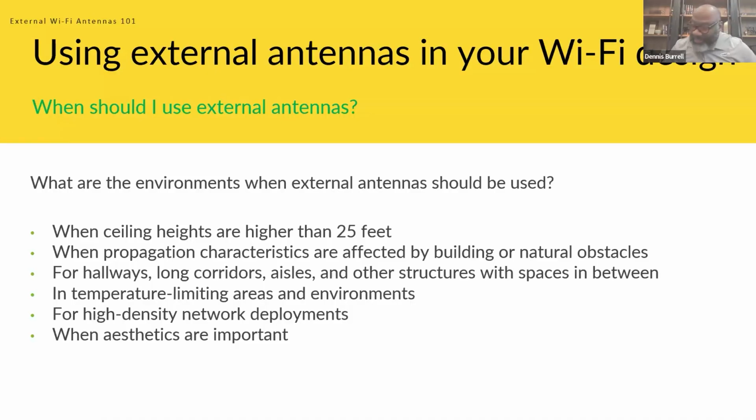For an omni antenna, let me give a little example. Typically when we do omni antennas, that radiation pattern looks like a donut. You've got your donut here. The thickness of the donut is your vertical. The hole of the donut is that null at 0 and 180 degrees. And then that circumference is your horizontal beam width, that 360 pattern. So that's the omnidirectional pattern.